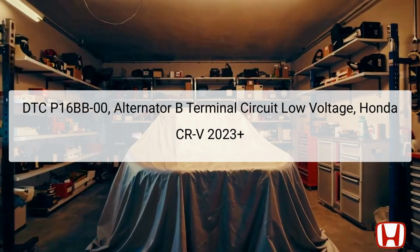The DTC P16BB-00 indicates a fault with the alternator B terminal circuit, leading to low voltage readings, which can prevent the alternator from correctly charging the vehicle's battery. This diagnostic trouble code, DTC, is crucial for identifying power supply issues related to the powertrain control module, PCM, and the alternator. The PCM monitors the voltage supplied from the alternator, and if it detects that this voltage is outside the expected range, it flags a problem by setting this DTC.